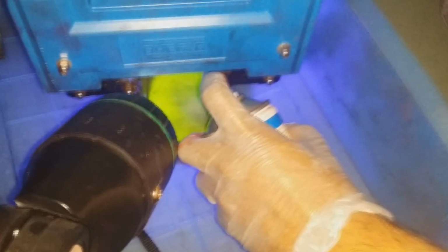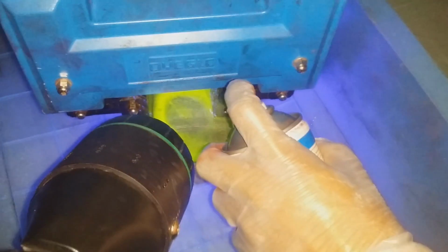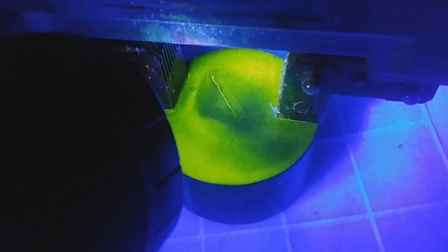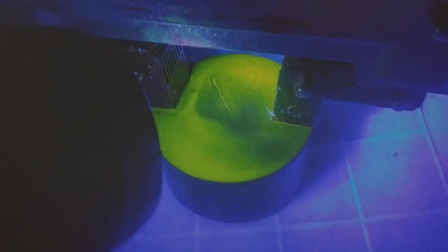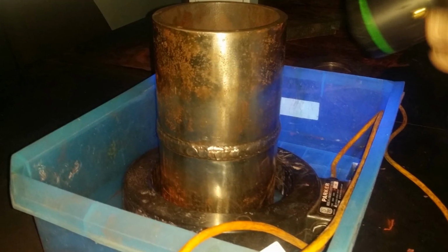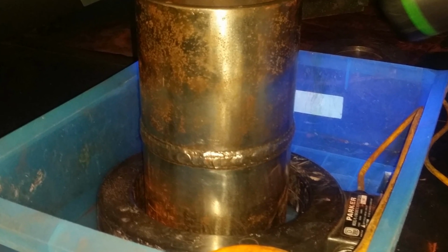While the yoke is still energized, gently wash away excess. Turn on the UV black light. Observe the inspection area during this process to witness indication formation. Evaluate indications to specification criteria prior to yoke reorientation. Turn the yoke 90 degrees and repeat steps 1 through 6. And you can do the inspection in the same conditions with the portable magnetization coil PL8 or PL10.